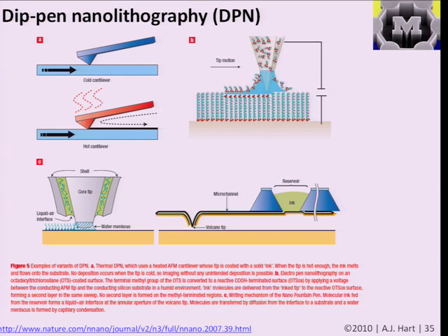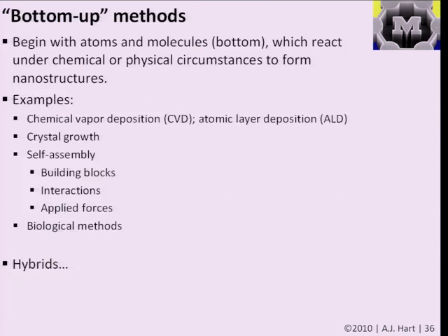For example, you can heat the cantilever and use it to write lines in a thermally sensitive polymer. Or there are advanced geometries of tips, for example, using a cone of liquid to focus the assembly or increase the resolution at which the droplet forms. And you can, in principle, also use this to deposit multi-layers: make one layer of molecules, and then change the tip or change the ink and put another layer of molecules on top of those.